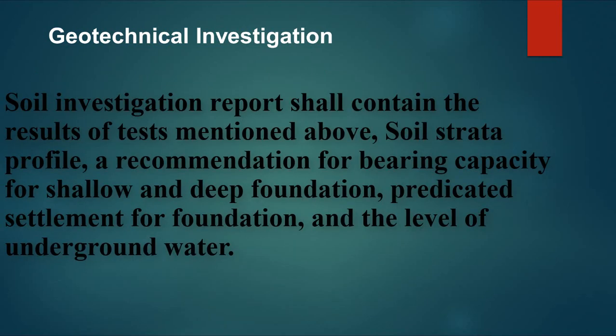concrete. The soil investigation report shall contain the results of the tests mentioned above, the soil strata profile, a recommendation for bearing capacity for shallow and deep foundations, predicted settlement for foundation, and the level of underground water.